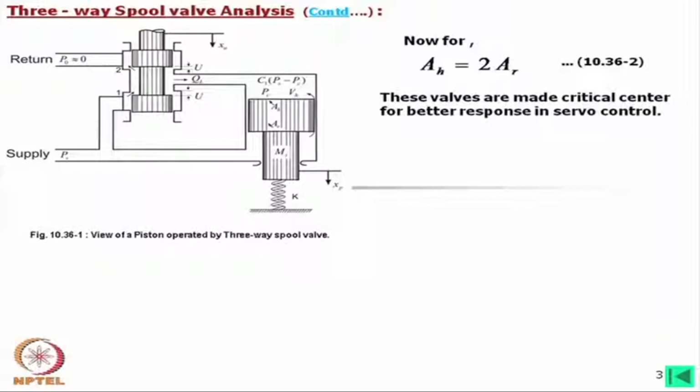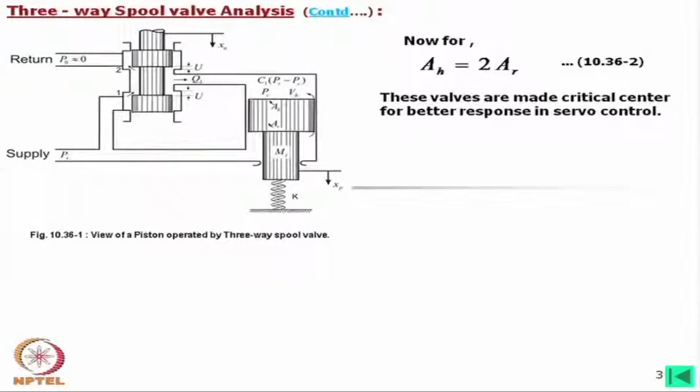That means, say 10 sets of spool and 10 sets of outer members are taken together, and each and every spool is matched with the outer member, and then it is examined how critical the center really is. The best pair is taken for one valve, then perhaps the next one. In that way, it may happen that in 10 sets of these two components, these pairs, 5 components may be rejected also. This is one thing.